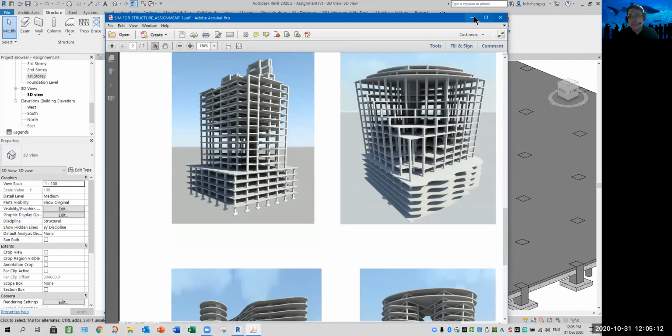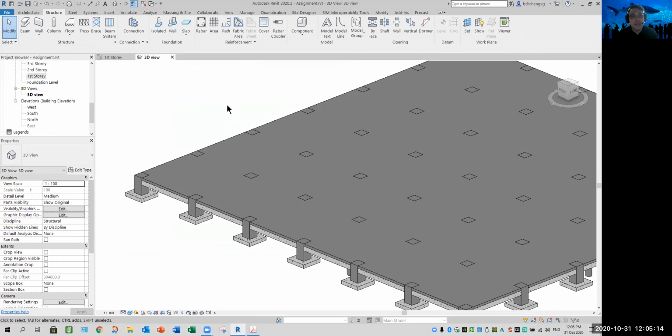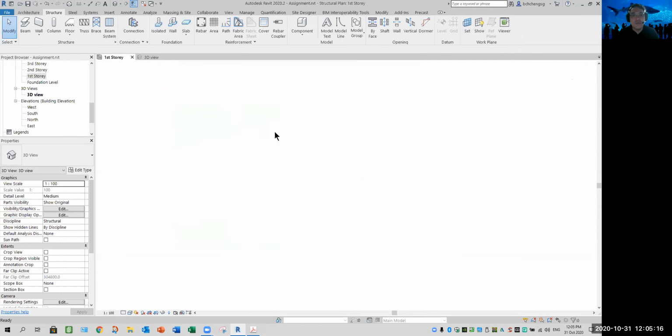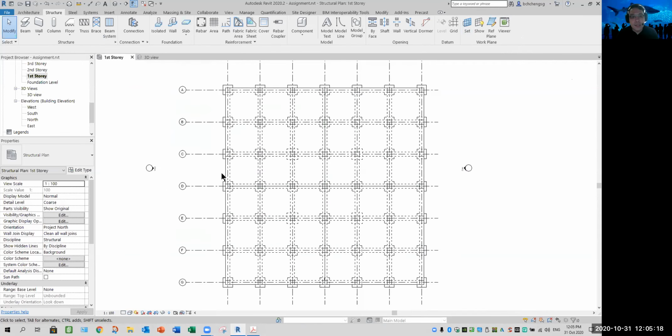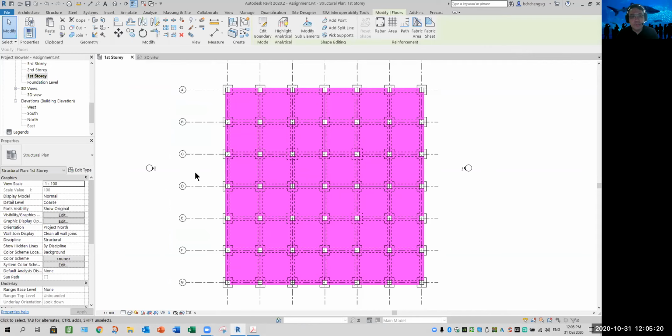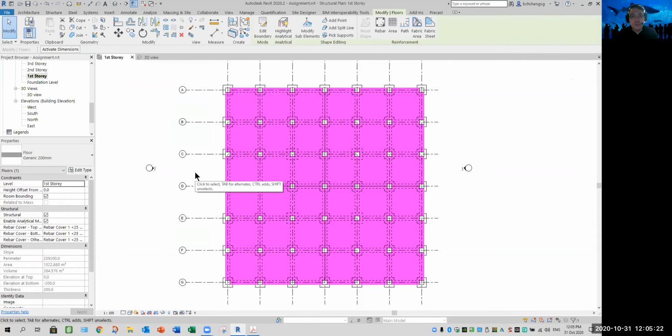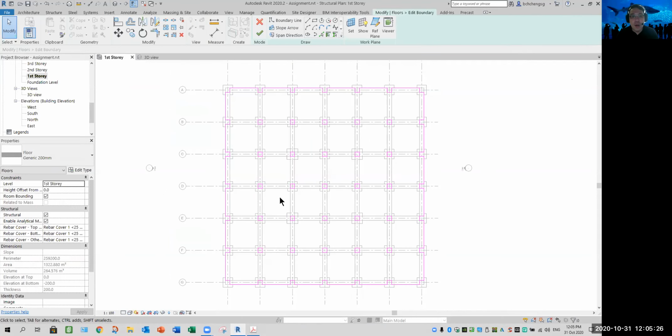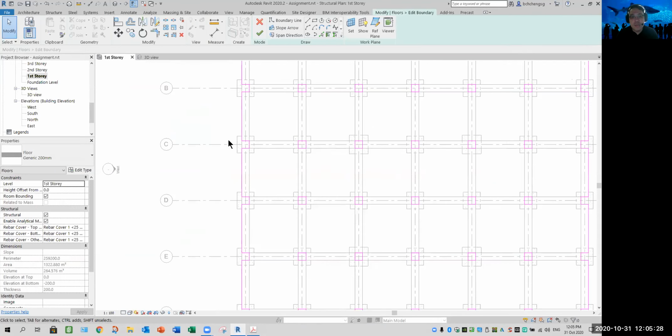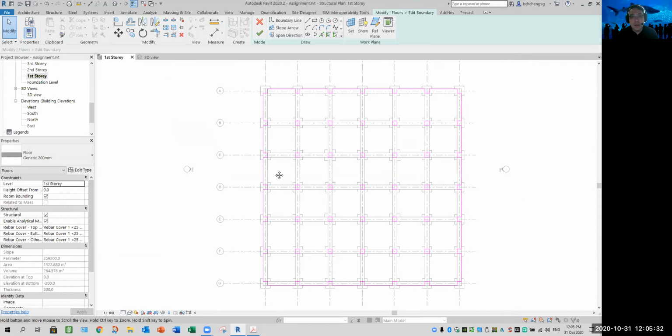Okay, let's give it a try. Let's say I wish to modify, selecting my slab, what should you do? Edit. Let's say I want to have an extension, same as my footing here. What I'm going to do now is select some of the lines to delete.